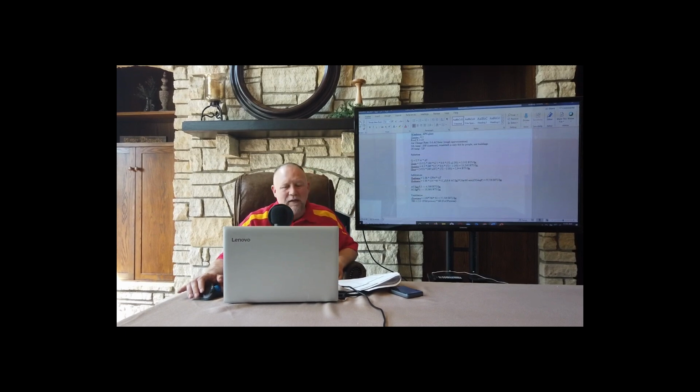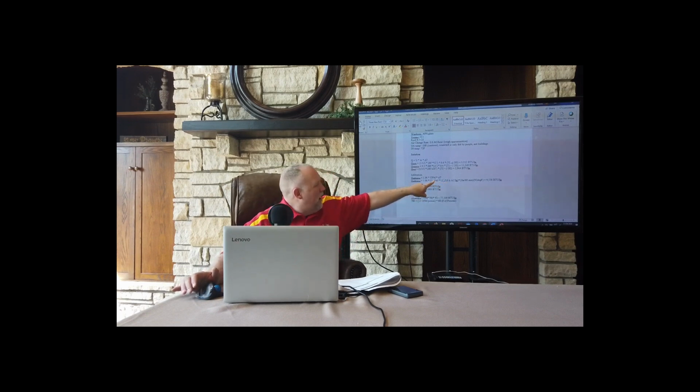Next, let's go down to the infiltration equation. Remember, write the equation you used and then write out all the individual pieces. 1.08 CFM delta T. All right, but we didn't give it in cubic feet per minute. I listed it in air changes per hour. So I have to multiply that by the volume of the room.